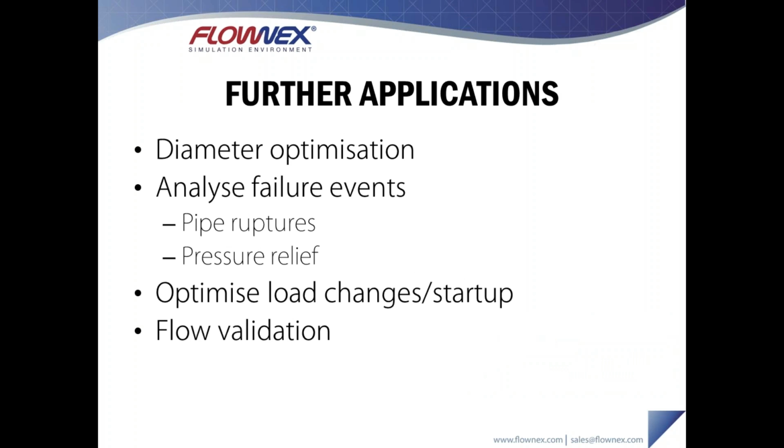Okay, finally I'd like to talk about a couple of additional applications. So as I mentioned, Flownex has an optimizer tool. We can use this for cost optimization in sizing our pipelines. So we have the Excel functionality built into Flownex, which allows us to take information such as the diameter of a pipeline and the power demand from a pump, perhaps.